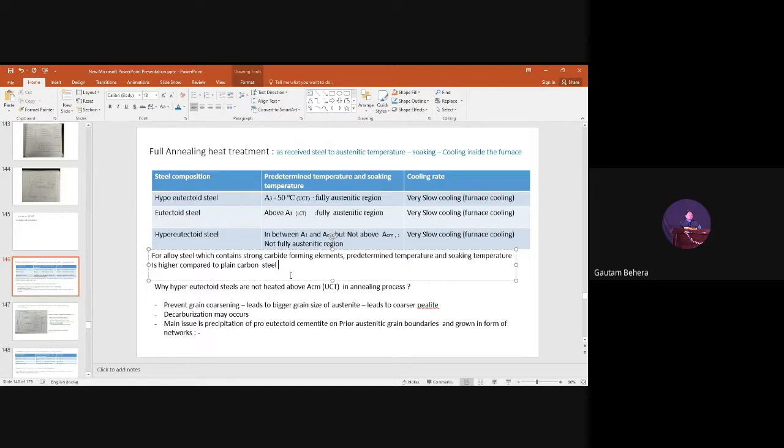Okay, do you people remember at 850 degrees centigrade, or above, like 750, 850 nearly, which carbide will get dissolved in the steels? Which kind of carbide gets dissolved? Cementite, yes, very good. Cementite is easily dissolved into the austenite phase. But if you have vanadium carbide, niobium carbide, titanium carbide, some alloying carbides, they are very difficult to dissolve. They need a very high temperature, right?